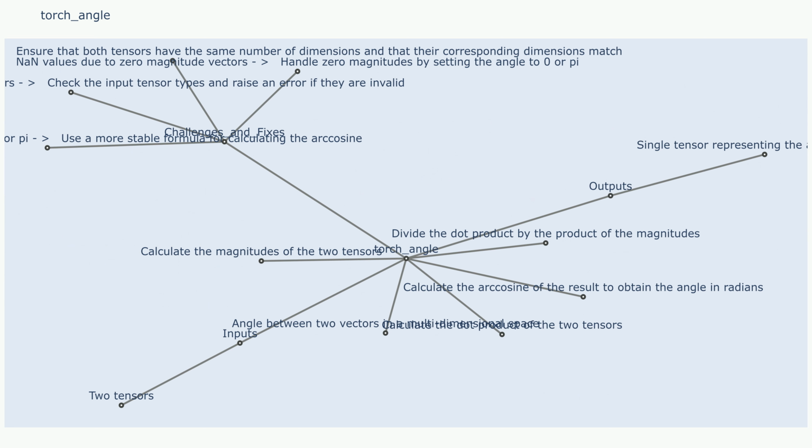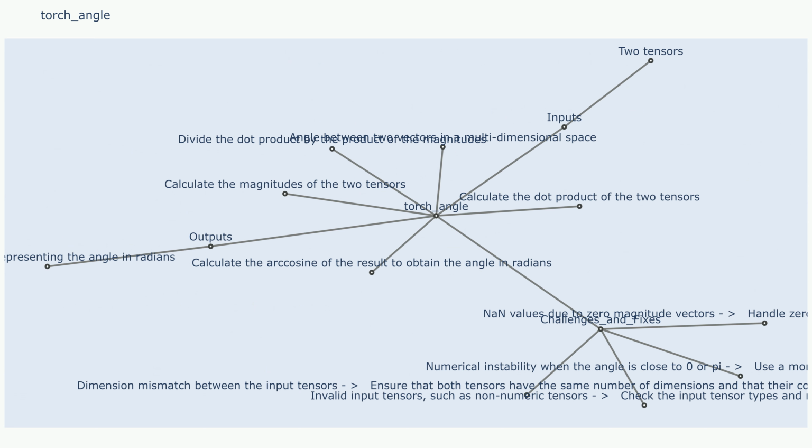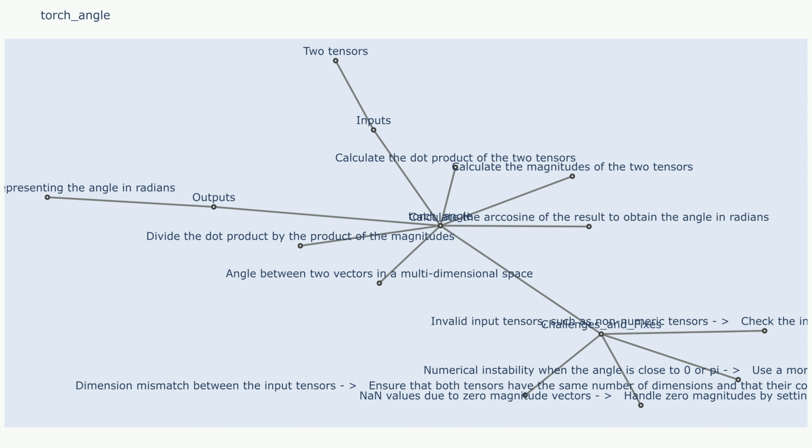Challenge 2: insufficient penetration. If the torch angle is too shallow, the weld may not penetrate deeply enough into the base metal, leading to a weak or incomplete weld. Sample use case that resulted in challenge 2: a welder welding a thick piece of metal with a shallow torch angle, resulting in insufficient penetration. Fixes to challenge 2: increase the torch angle, raise the torch angle to increase the heat input and penetration.